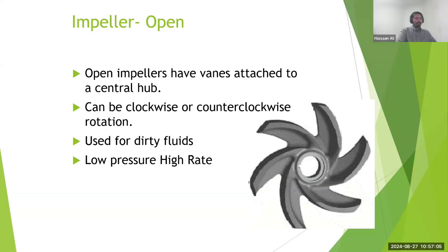Very good question. Submersible pumps do not need to be greased or lubricated. The submersible pumps are designed in a way that, in some of the submersible pumping systems that I'm aware of and have worked with, they have something called a protector or a hydraulic compensating unit, which has the lubricating oil in it. That ensures that the seals and the bearings are always coated in oil. So it is a self-contained unit in the submersible pumps. That's why they are submersible, because you cannot maintain them as frequently as a surface pump.